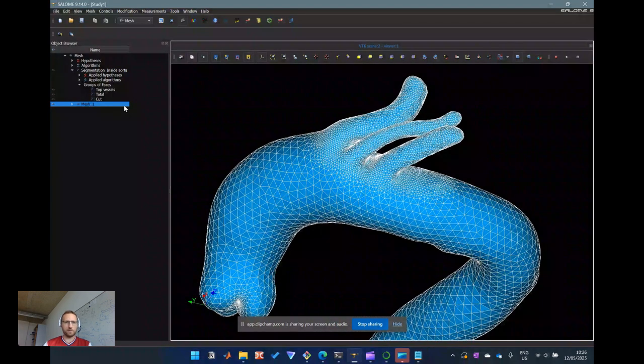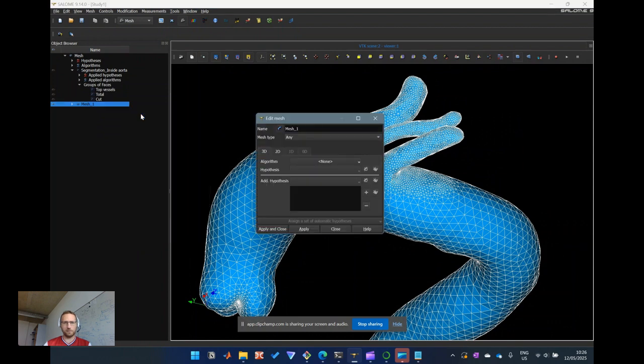And so now, having this mesh, we can click on the edit, and now it can create a tetrahedral mesh where we just select NetGen 3D, and don't forget to remove the surface meshing because we don't need it anymore.